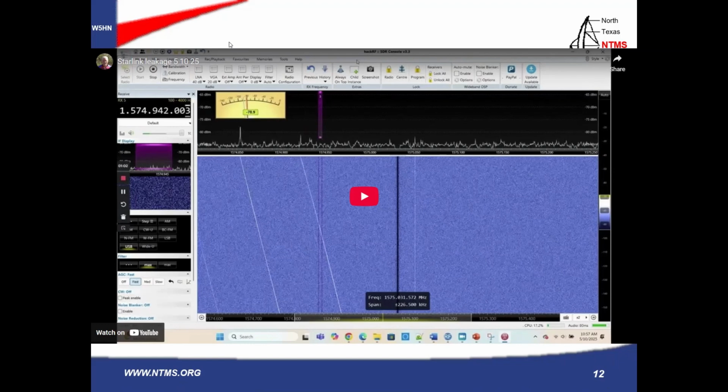Sadly, it's 10 megahertz. And what we're receiving is that crap, if you want to call it that, but it is the leakage tones and the comb. And seeing the comb itself confirms that it is between channel leakage.